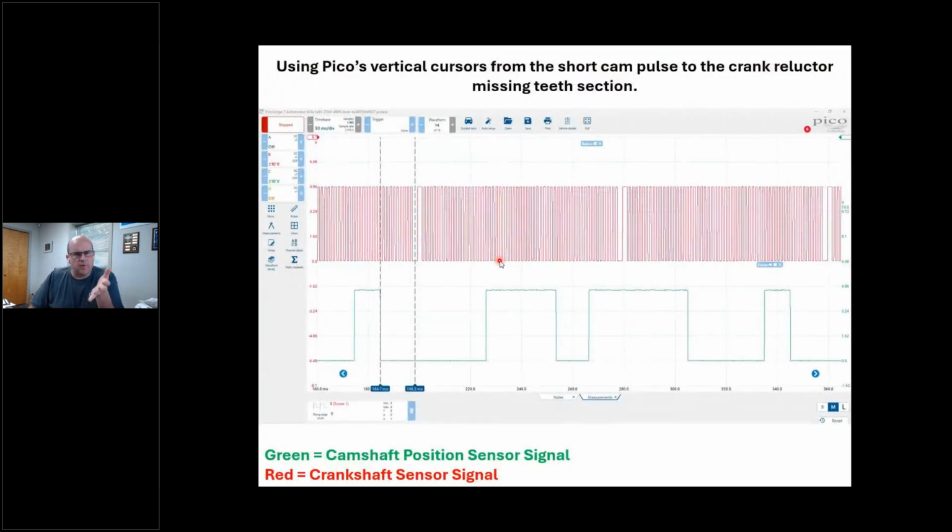Okay, so we're going to practice what I just showed you. I get on those same pins, 32 and 33 of this truck. I fire it up. All right, you don't even have to run. I can do this test cranking. It just happens to run. Okay, so let's say it's way off and it won't start. I can get on here and check the synchronization, no problem. So I get on these 2 wires. I roll this thing over. It fires up. I maybe only let it run for 5-6 seconds. I got what I need.